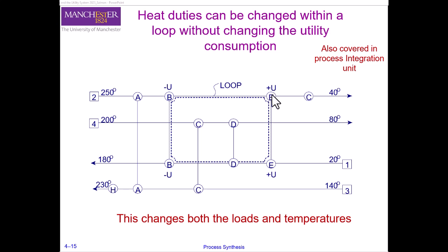So what we can see here is that we have actually shifted some heat duty from this exchanger to this exchanger, and by doing that we change the size of this exchanger, but also the temperatures of the streams around these exchangers.